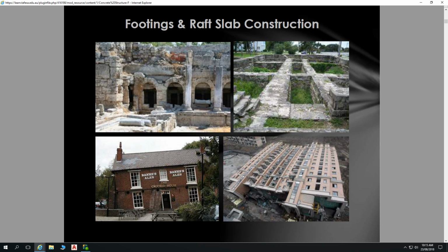In a post-tension one, it can release that strain all the way through, because the grout doesn't have the same bonding capacity as the concrete. The concrete binds to that steel strand all the way through, whereas with post-tension, if I cut through one of these, the whole thing can go. So it's important to understand those performance aspects into the future as well.